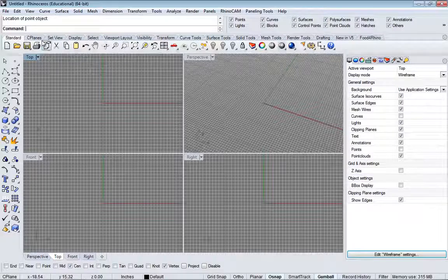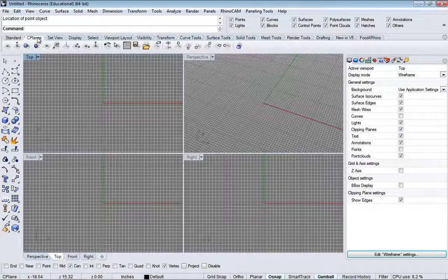So it's very good that way, and that's why it's very different than most other modeling software. So if we go to the next tab, it will be construction planes. You'll notice that for generally doing two-dimensional work or architectural sort of work, a construction plane is basically telling the computer what's the plane of surface that you want to create something on.